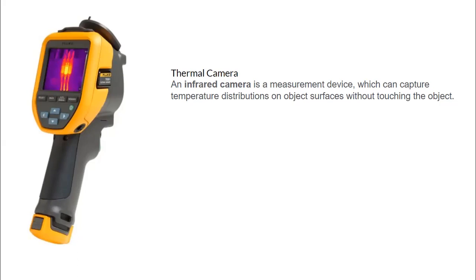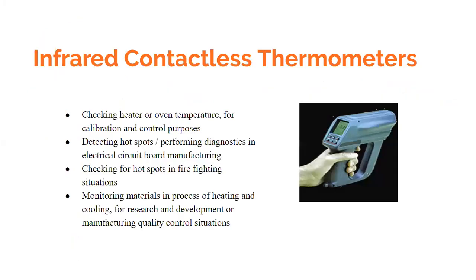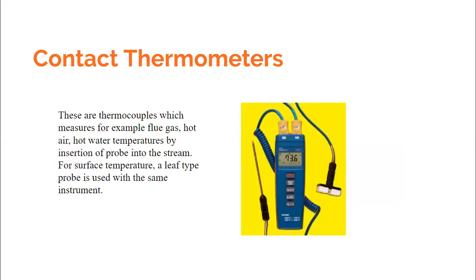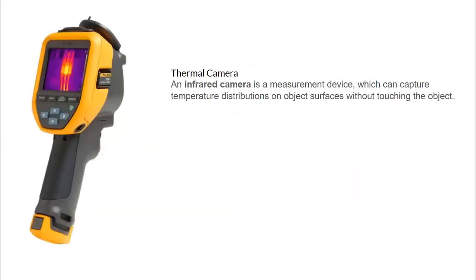So this is an extremely useful instrument in the audit, and again, obviously, it has an advantage over all the other two types of thermometers, because this is a thermometer which simply gives you one temperature at one time, and you need to have physical contact over that surface. But with this you would simply get a photograph. You take a photograph of a particular surface, you can imagine that, and you get the entire image.